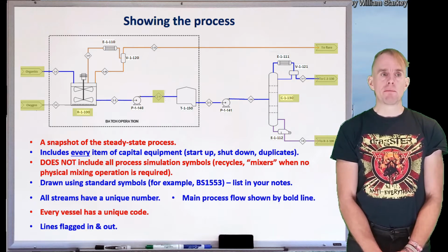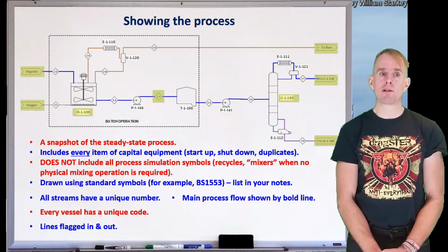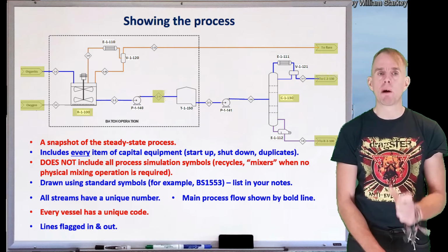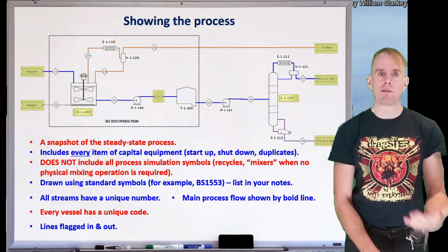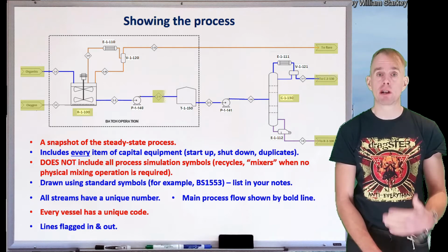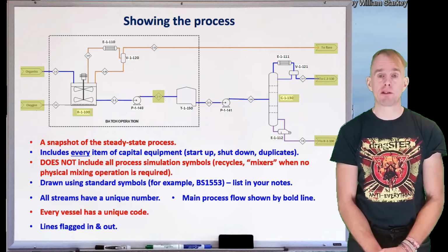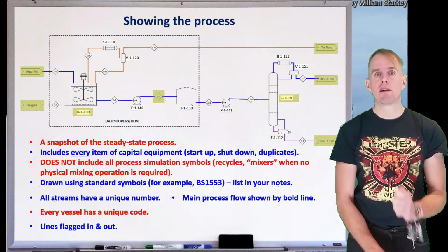Okay, what else can we see? Well, if we take a broad overview of how this segment of process is drawn, you'll see that the line weight and line colour differs. Now, it may not always be practical to have line colour. Very often process flow diagrams on plant are going to be shown in black and white, especially if it's an old piece of plant with paper-based diagrams. But the line weight is very important.